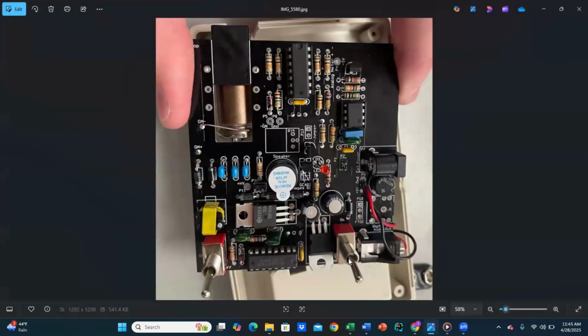Then here we have a picture of the actual board. So we have resistors all through here, resistor, of course, resistor, Zener diode. Then we have normal diodes all through here, which are biased. Same thing with the Zener. Here's your speaker, then capacitor, capacitors, capacitor, capacitor. You have your LED. This blinks every time there's a radiation event.